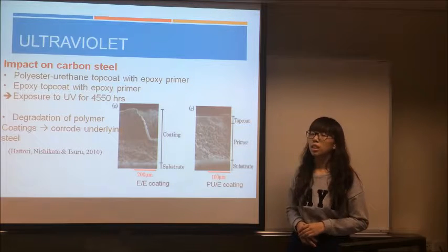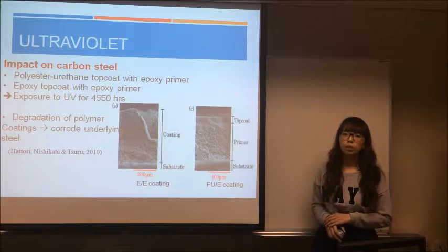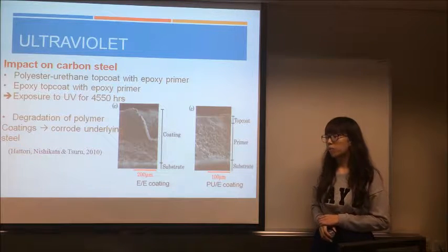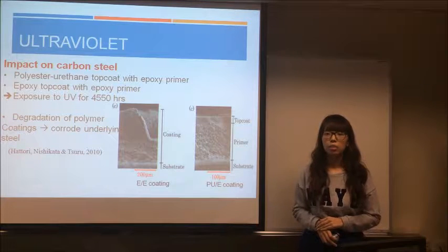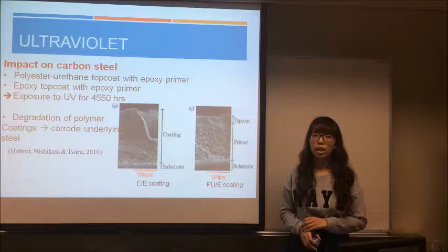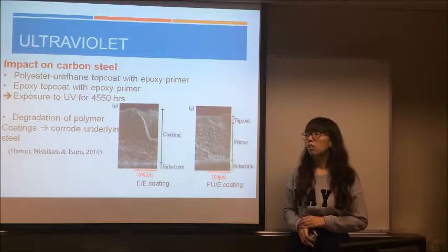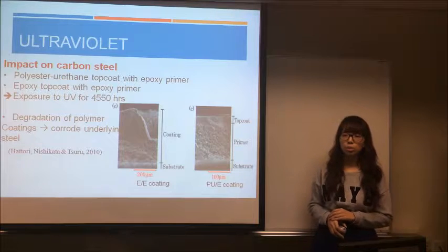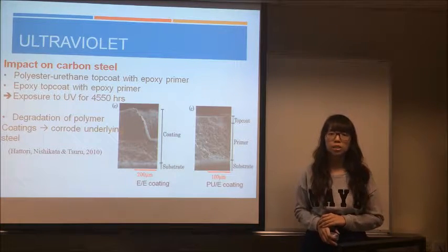They act as a barrier to protect the underlying carbon steel from corrosion by environmental factors, such as ultraviolet and rainfall. However, the dissolution of the steel can happen at defect sites on the paint, or the compensating oxygen reduction may occur at the other steel surface under the paint.